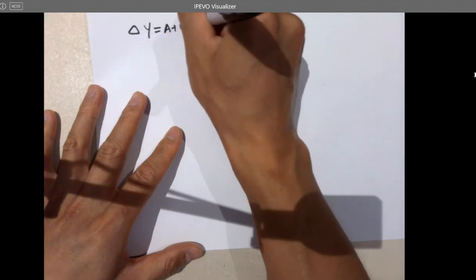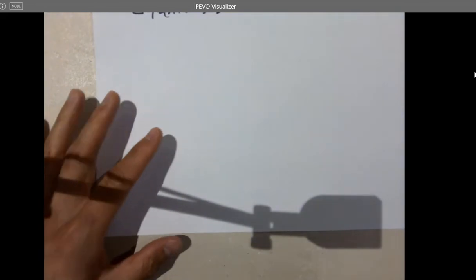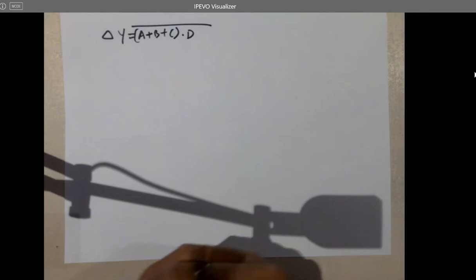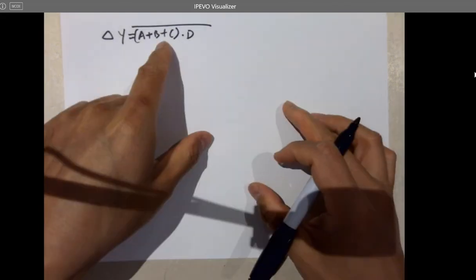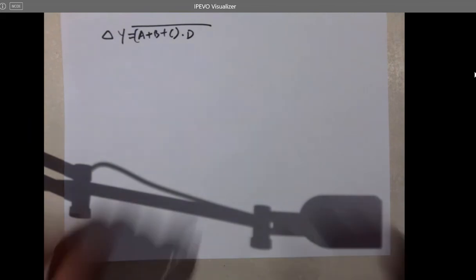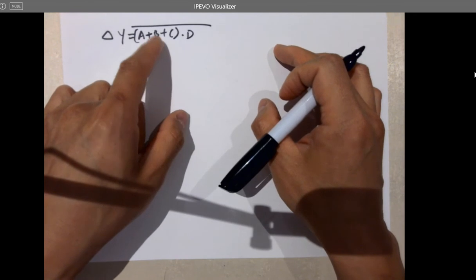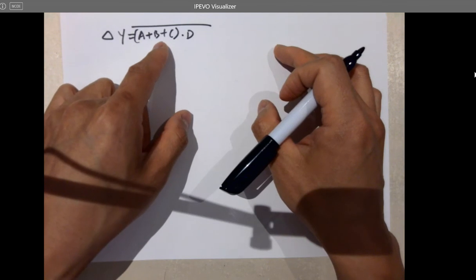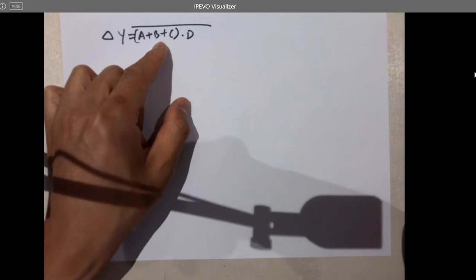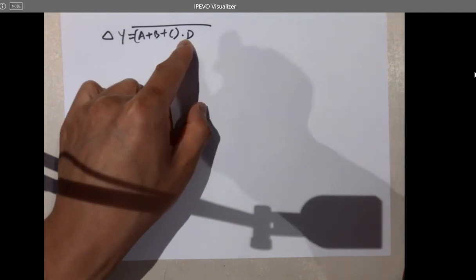A or B or C and a D not. So remember how we design a complex CMOS circuit from Monday this week? We start from converting everything into a something bar, right? First. And if you have a NOR logic, you need the PMOSes in what on the top? Always think about the NOR gate. So the PMOSes are in series and NMOSes are in parallel. For this NAND, you need PMOSes in parallel and NMOSes in series, right?